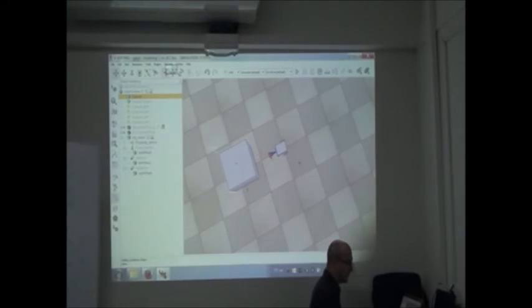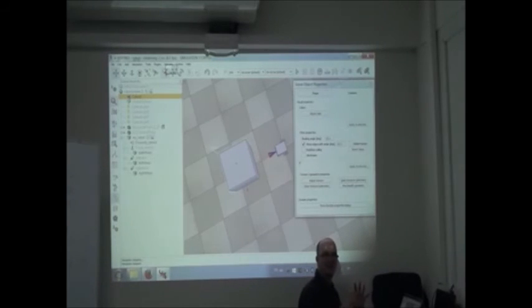Now, this dark red detection cone will be turning pink if I detect something. So let's see if it goes. It should turn pink when you touch, and it's not doing it. Why? Because you have to know that by default, the cuboid is a dynamic object, not detectable by default. So it's collidable if I go there. No, right. It will be colliding. Oh, we are in collision, but it's not detectable by the sonar.